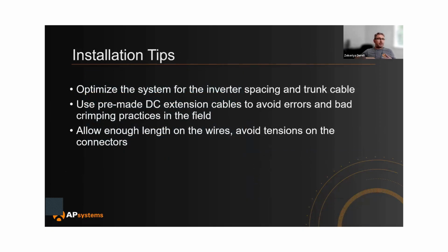Just to give you some installation tips based on the things that we discussed. Inverter spacing is important, trunk cable is important, so you may want to optimize around that. Don't run the trunk cable from here to there. Try to run a straight line. Keep the inverters close to each other, so you can use a 2.4 meter trunk cable, or 4.6.